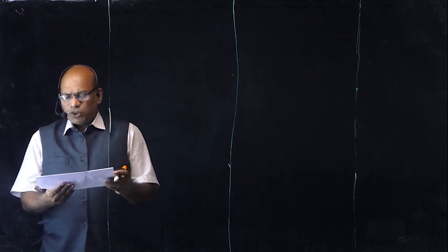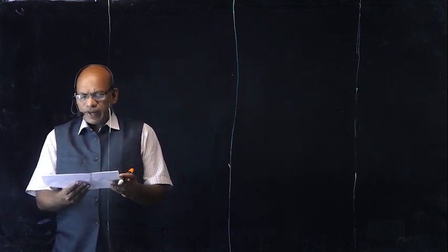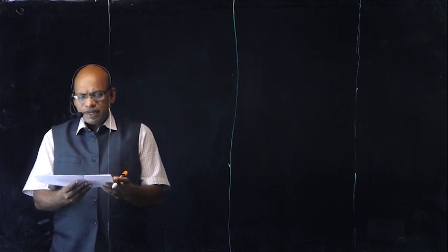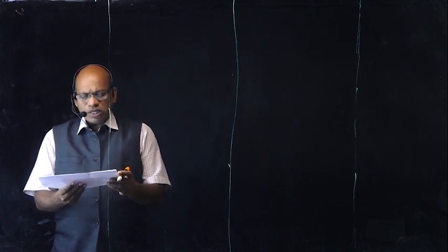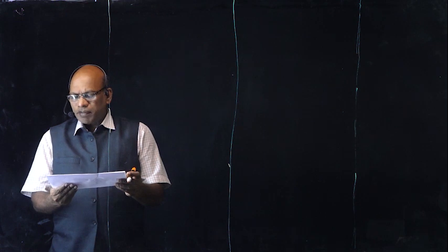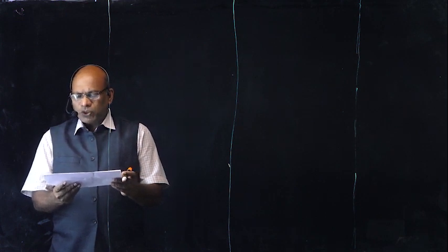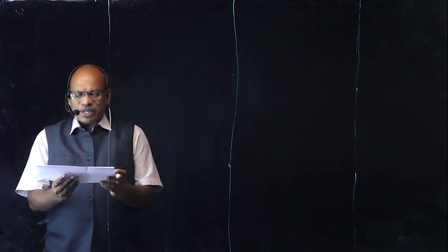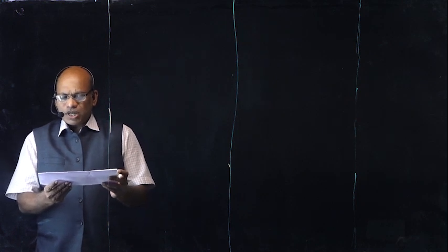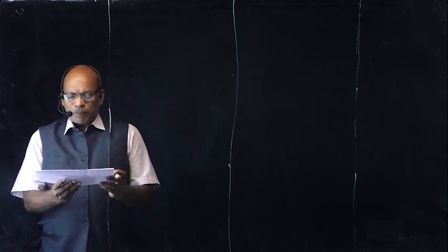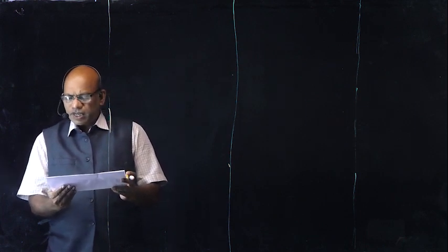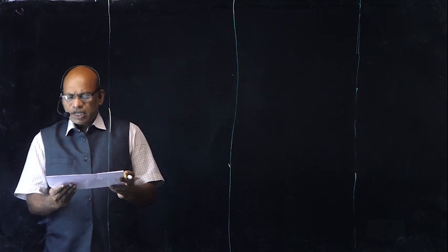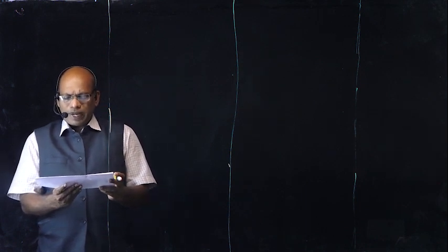A pitot-static tube placed in the center of a 300 mm pipeline has one orifice pointing upstream and the other perpendicular to it. The mean velocity in the pipe is 0.80 of the central velocity. Find the discharge through the pipe if the pressure difference between the two orifices is 60 mm of water. Take the coefficient of pitot tube as